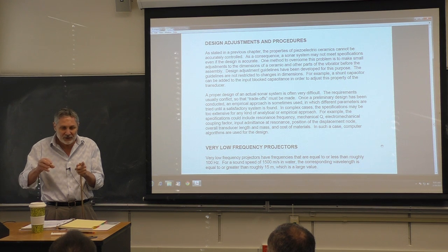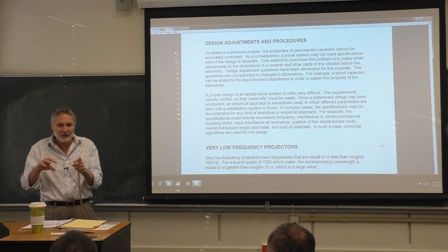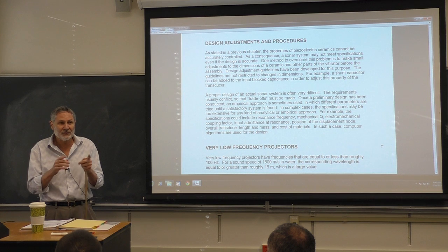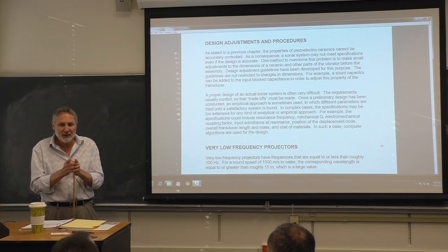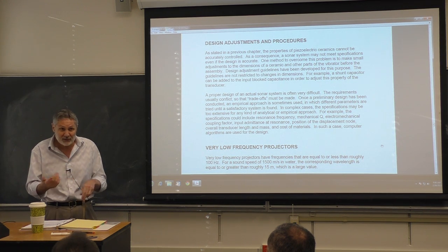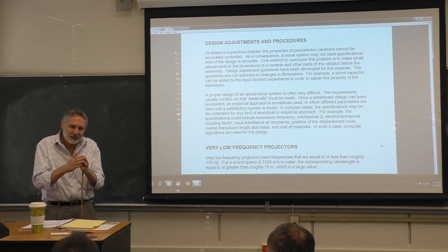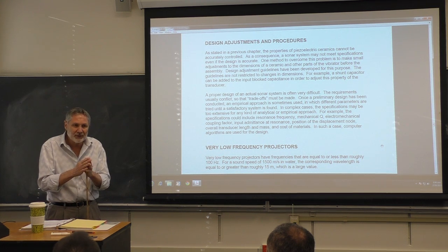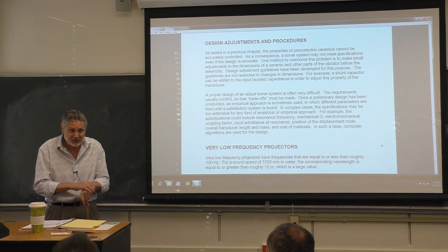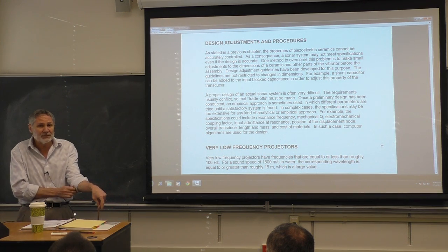Now that I could adjust, we put a potentiometer on it. We tuned that to the sensitivities the same. But what made the thing fail was the phases were different. I have no idea how that could have happened. These were piezo-resistive microphones. Okay, that's kind of weird. When a sound wave comes in, it stresses the material and it causes a change in electrical resistance. So you can use that to pick up on sound.